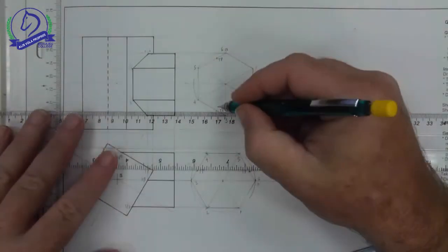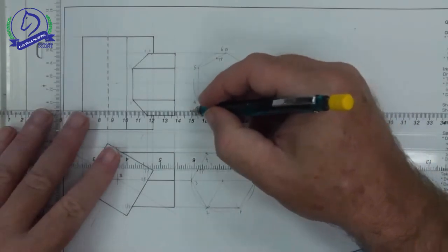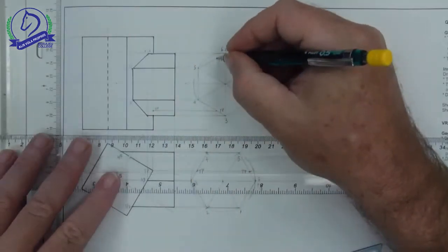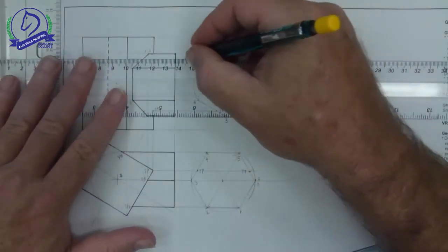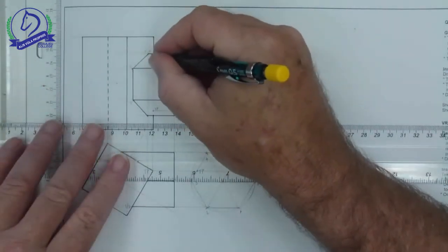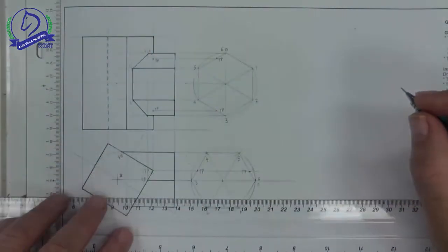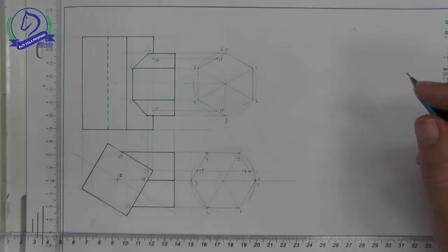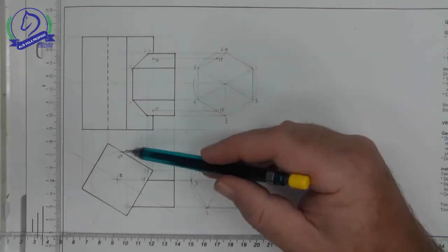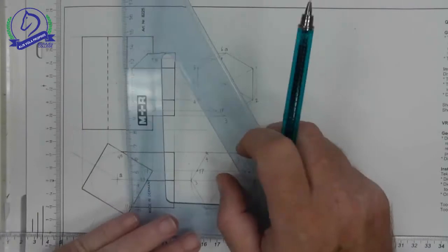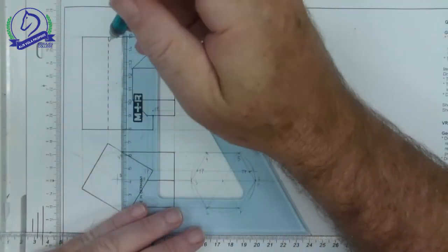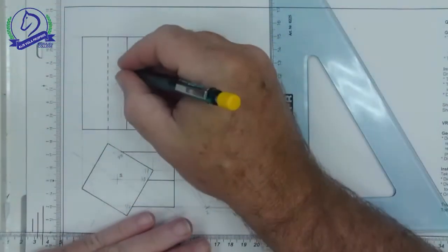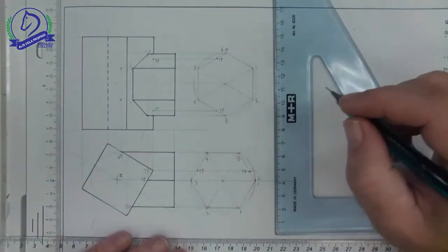Let's match these points up. Project this across to hit my turning point line. There is my turning point at the bottom. Project that across to find the turning point at the top. The last 2 points will be points 4 and 5. So we project points 4 and 5 up from where it hits the branch pipe to where it hits points 4 and 5 on this side.